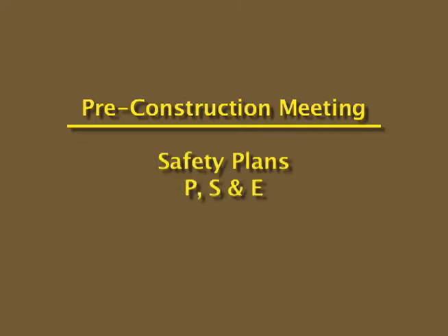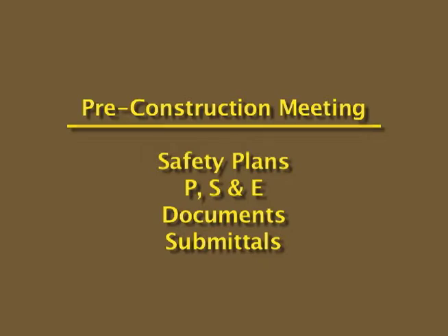So the first thing we do for construction is conduct a pre-construction meeting, and at that meeting we set the tone for the project as to what the expectations of the parties performing the work are. Typically at the pre-construction meeting we'll go over the safety, go over the plans and specs and discuss those, and make sure there aren't clarifications that need to be made. We'll collect the necessary submittals for the project.